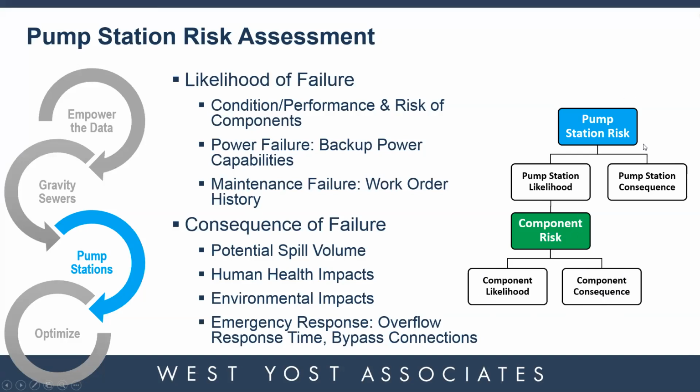Then we drill that up to the pump station level. And we start to look at other factors like spill volume, human health impacts, very similar to the gravity sewers, but also looking at emergency response impacts like overflow response time, bypass connections, and whether there are redundancy factors built in. Backup power, of course, can affect how likely this station is to fail.